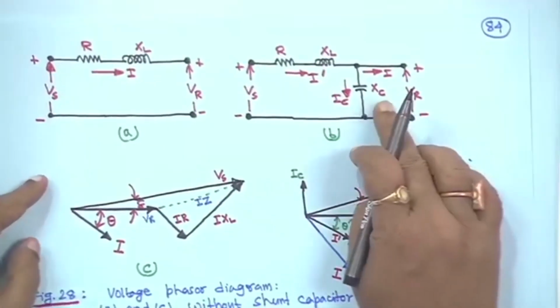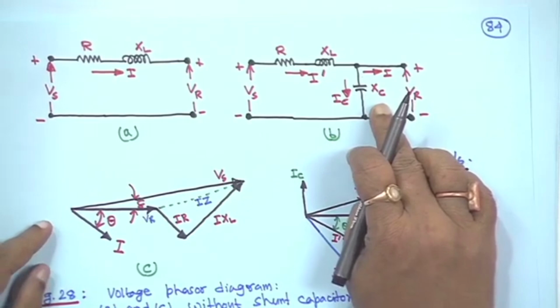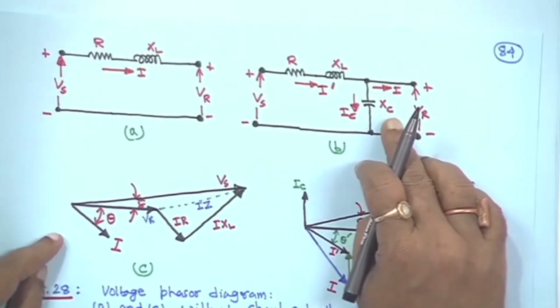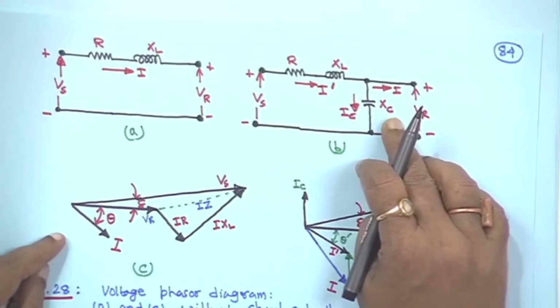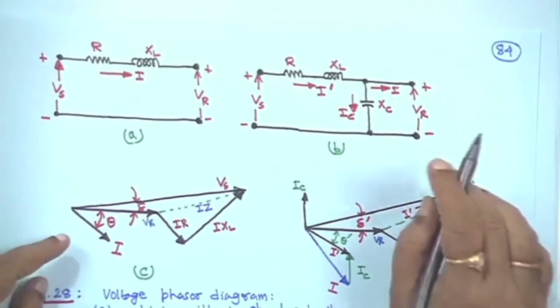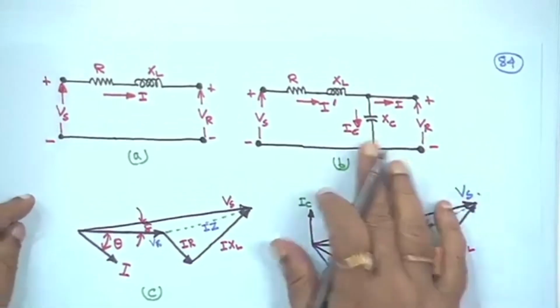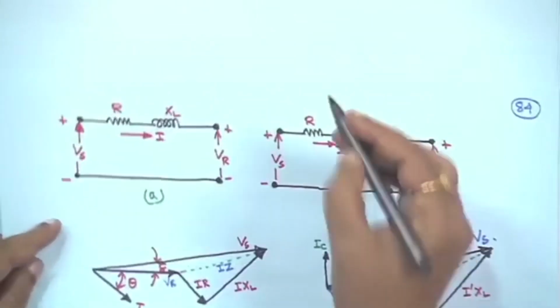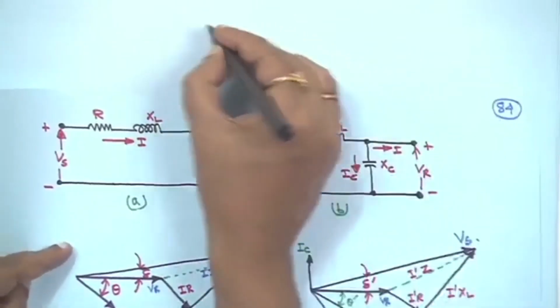For example, this diagram. Now, Xc is the magnitude, that is the reactance, 1 upon omega c. As the capacitor is a constant impedance type of load, because Xc is equal to 1 upon omega c, we assume that omega is not changing, because if we assume a 50 Hz or 60 Hz system, generally f remains more or less constant. So, reactance remains constant. Now, take this simple circuit. I will take only the magnitude. So, this current magnitude IC